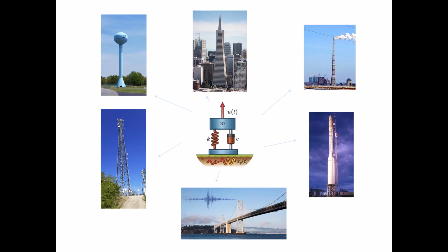And chimneys, smokestacks, even rocket vehicles on the pads, they're like these tall cantilever beams, and if they're being launched from, say, Vandenberg, California, near the San Andreas Fault, then an analysis has to be performed to make sure that launch vehicle can withstand a potential earthquake, even if it's just going to be on the pad for a week or two prior to launch.